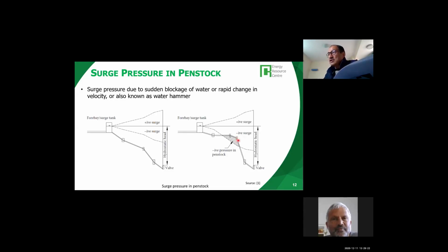on this penstock. So when you design this penstock, number one, you make sure that the alignment of the penstock is such that you don't create a negative pressure on the penstock. The other thing is you design the penstock diameter to manage not just the normal hydrostatic head from here to here, but also the positive surge.